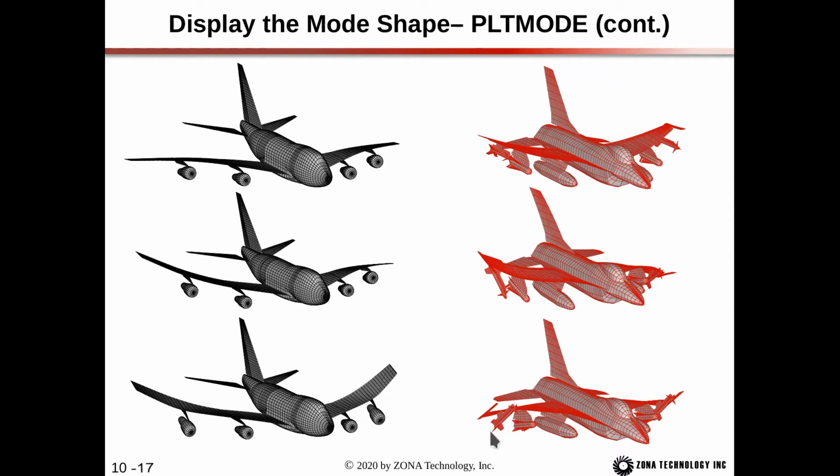Likewise here, this underwing store is following the motion of the wing. So this indicates that we have a proper spline setup. And of course, you can also compare this mode shape visually to your structure mode shapes. When you compare those two, they should look similar.